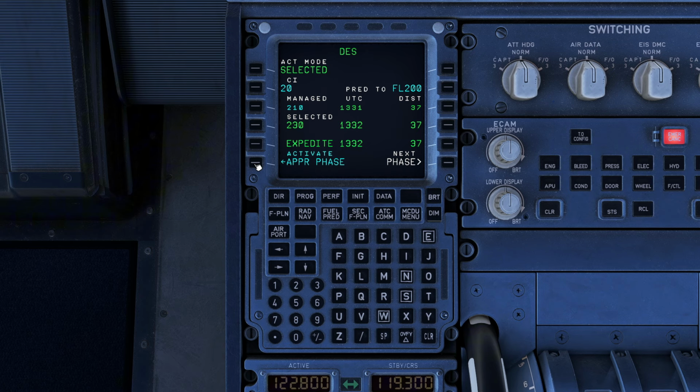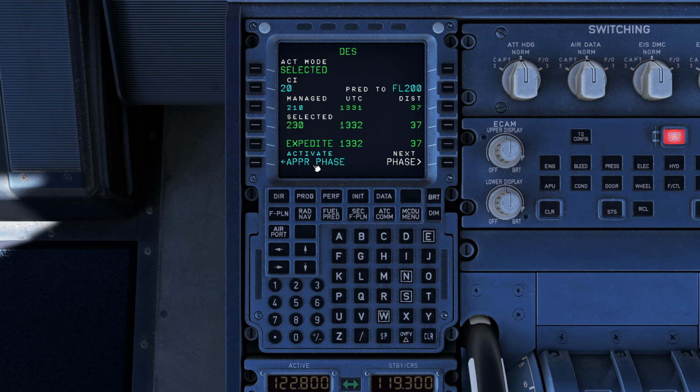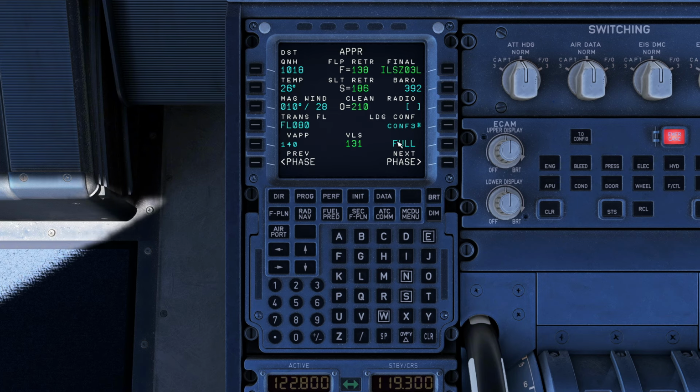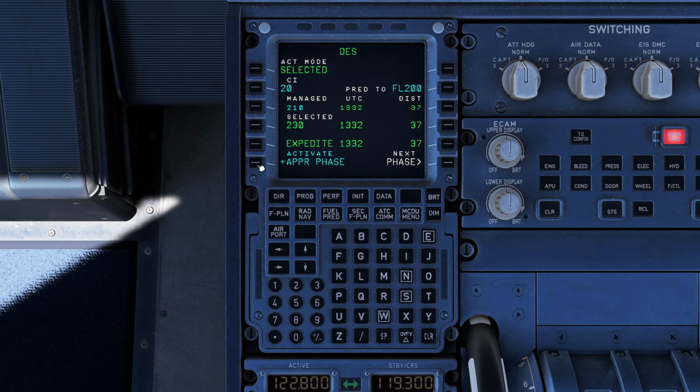If we prompt this one and confirm this option at the next stage, the aircraft will reduce the speed toward VAPP, but according to the configuration of the aircraft, initially the speed will be reduced to green dot speed, which you see here, which today is almost 210, or the speed constraint inserted at the final descent point, or FDP.